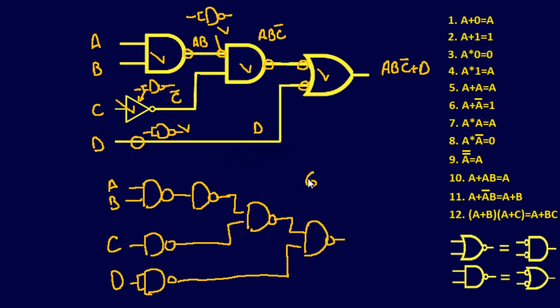which is going to take 2 7400 chips. Not bad for 6 gates. Whereas this one, 1, 2, 3, would actually require 3 chips just to utilize 1 gate and then 2 gates and another 1 gate. So you have a lot of extra chips and a lot of real estate that you're wasting, in a sense. Space is a big deal when creating circuits, as well as cost. By using 2 chips and minimizing space, you're saving a lot of money and creating less hassle and fewer headaches. So let's go ahead and check our answer.